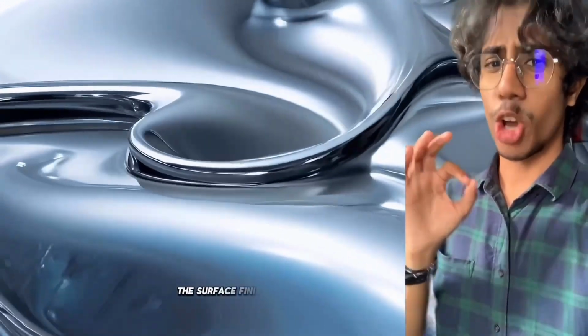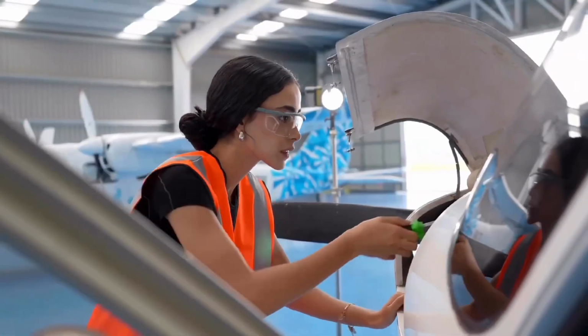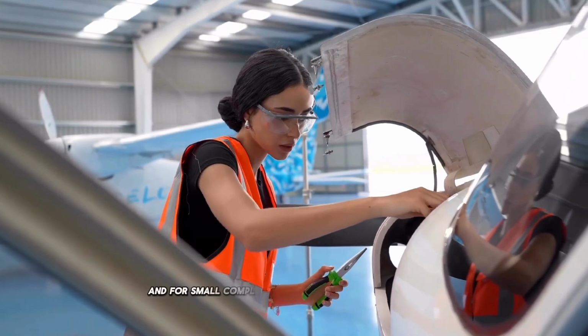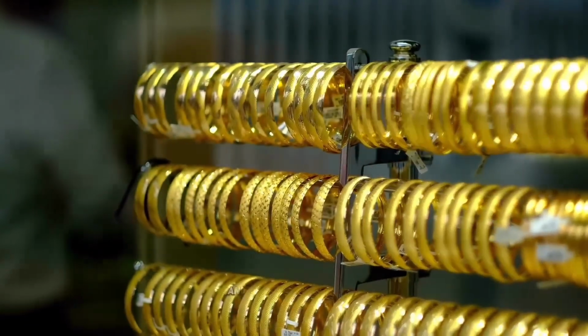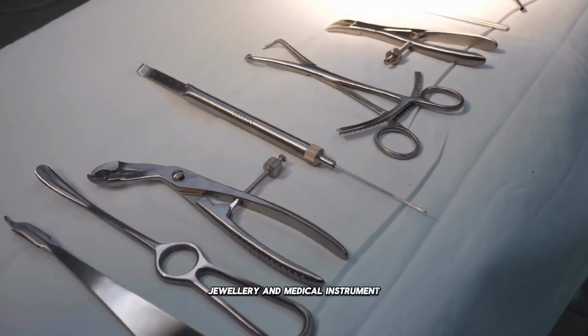The surface finish is very smooth and detailed, making it ideal for intricate parts. This process is suitable for small to medium production and for small complex parts that require high accuracy. Investment casting is expensive and it is used in aerospace, jewelry, and medical instruments.